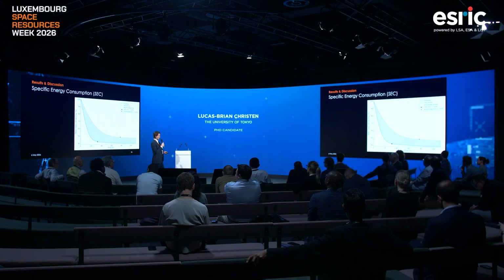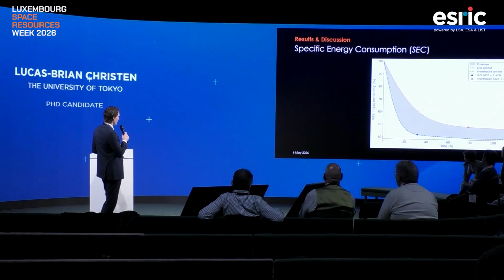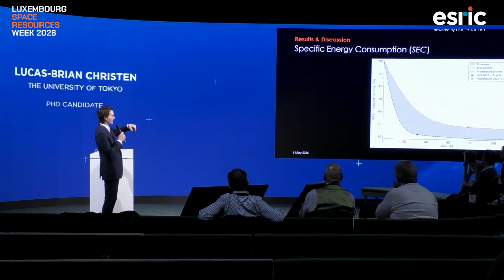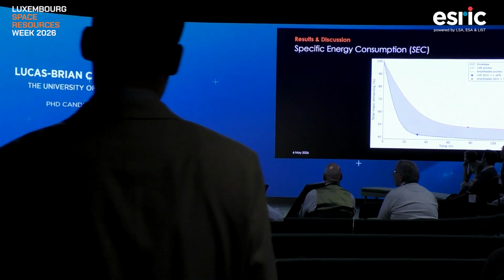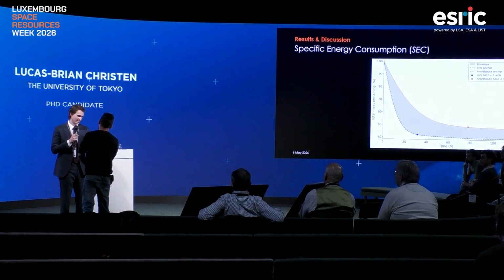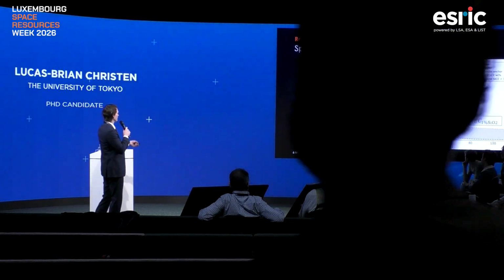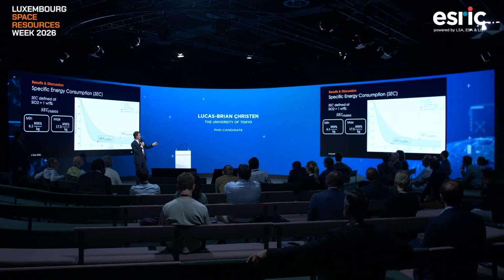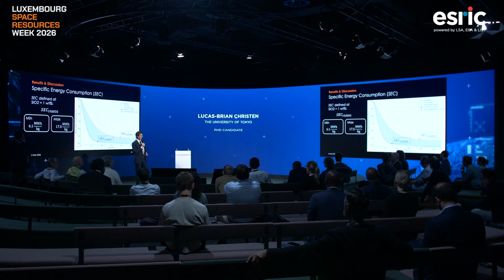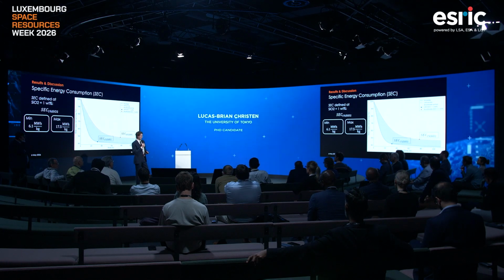And what's interesting about this is we can now know the energy consumption that we need to put in to drive that total mass down until we reach 1 weight% of silicon dioxide in the residue. That would be the specific energy consumption. We reach values around 10 megawatt hours per kilogram, which is quite a high number.